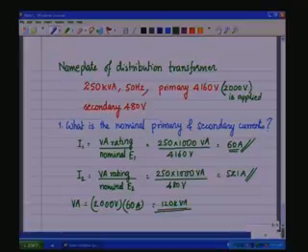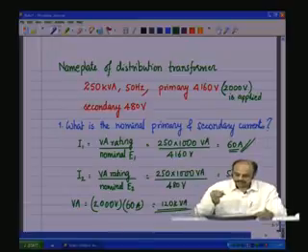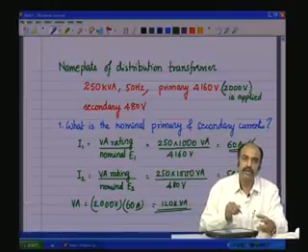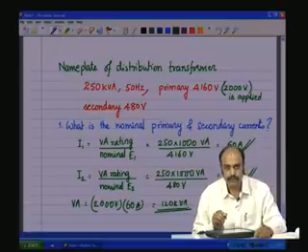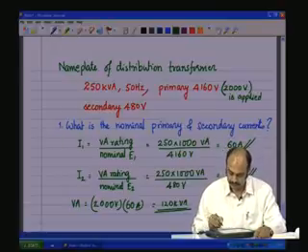So, to a 250 kVA transformer, if you are applying a lesser voltage, do not expect that it will deliver the whole 250 kVA, because it cannot handle the increased current, because the windings will not be rated for the increased current. Therefore, you have to limit the current only to the nominal currents, which is the 60 amps, and the nominal current into the reduced voltage will give you an apparent power which is considerably reduced with respect to the rated.